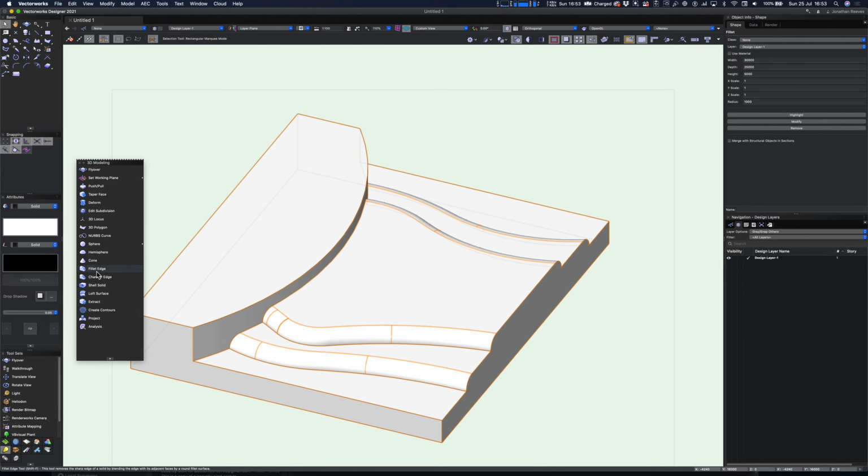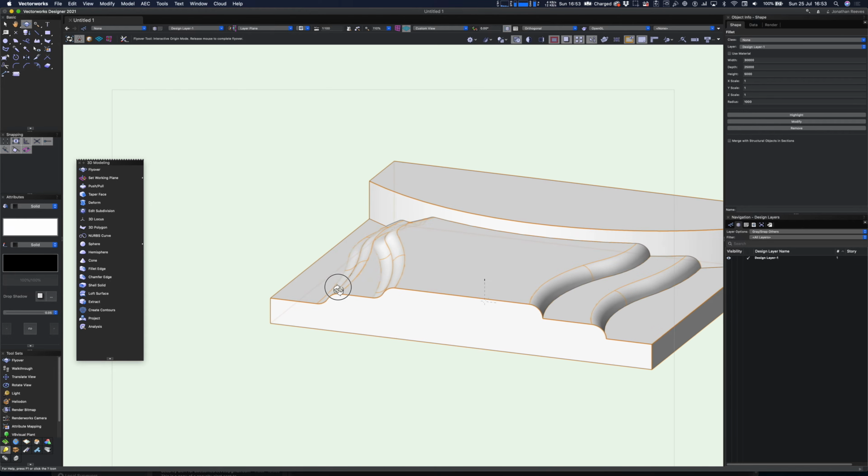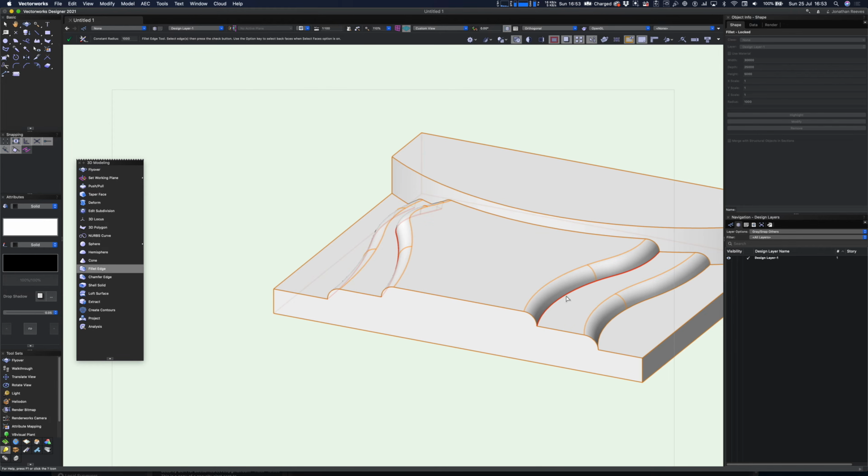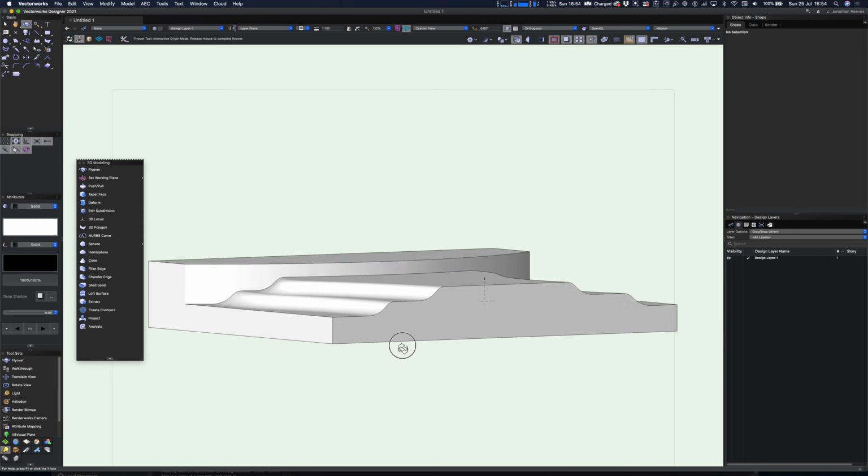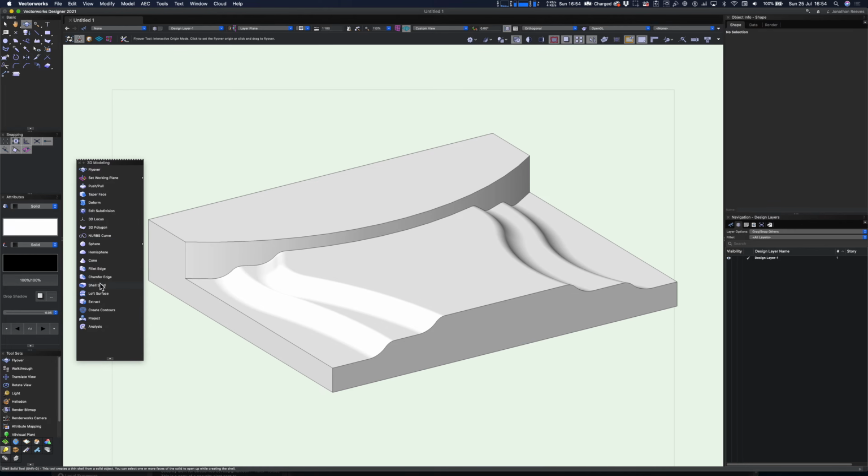Get the 3D fillet edge tool. I'm just going to basically select, holding shift down, these individual edges. Sometimes they get broken up. So brilliant, that's great. I can do both of those together, and we'll just go modify, select those other 2 edges, they're a bit cleaner, and click tick again. Now it's a lot more efficient to do all the filleting in 1 or 2 operations rather than sort of 4 individual separate ones. And the real beauty of that is you can then change the fillet radius, as I just did, for multiple steps. So already this landscape's coming on, it's looking quite nice. Again, we're just going to go and fillet this edge here.